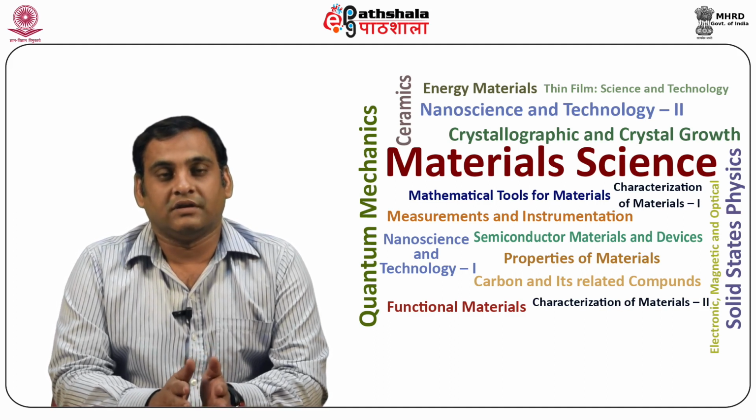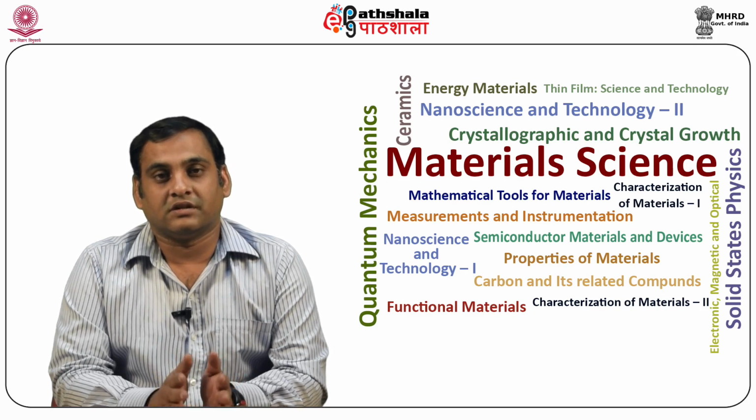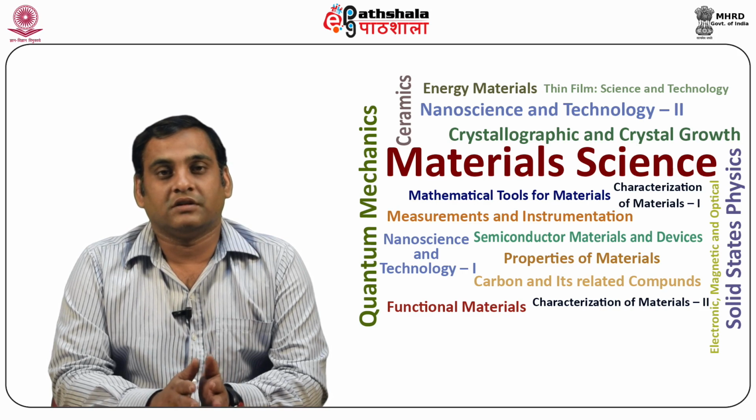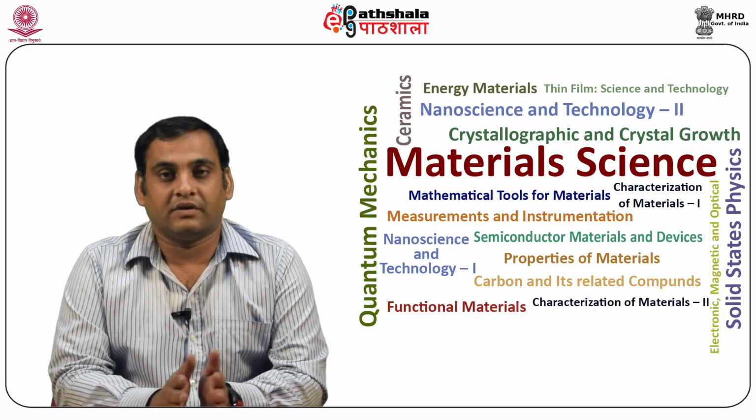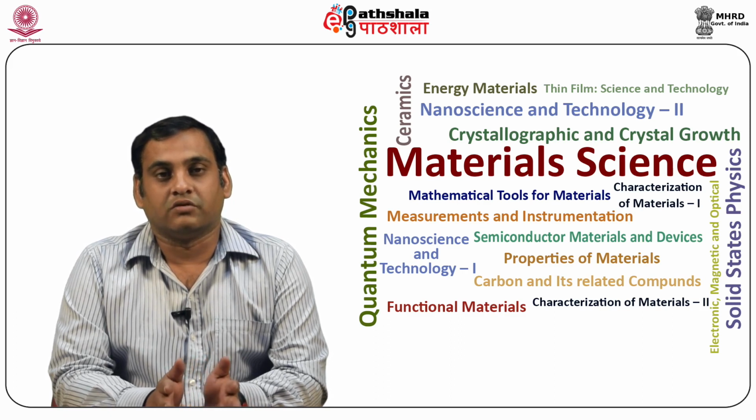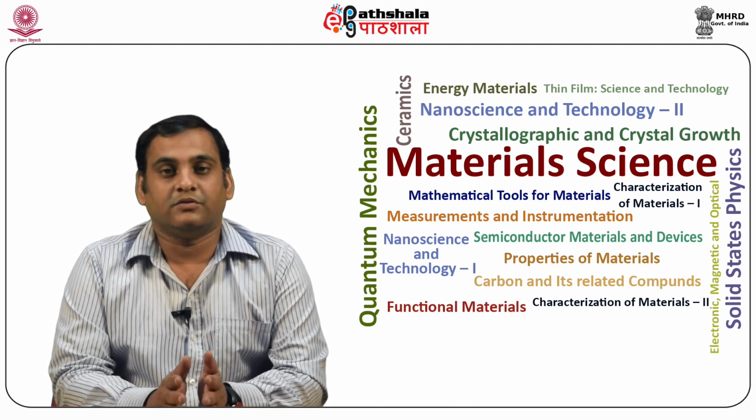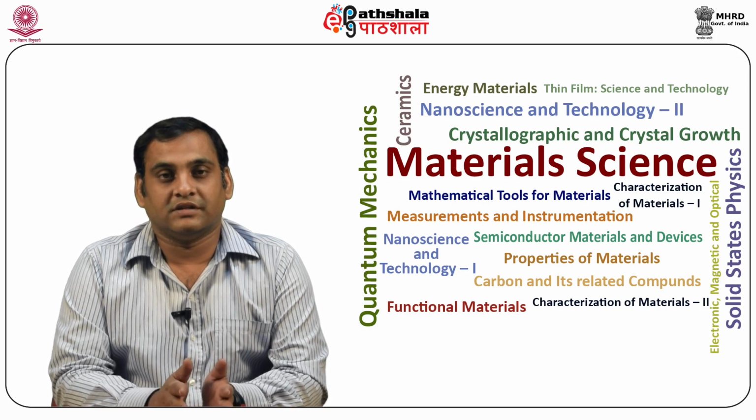Energy associated with a magnetic field. An expression for the energy associated with a static magnetic field may be obtained by considering an inductor L consisting of a current loop which creates a flux phi equal to L times I. By Faraday's law, epsilon is equal to minus d phi by dt, where epsilon is the electromotive force, or EMF, developed in a circuit and phi is the flux threading it. So, the power needed to maintain a current I in the inductor is epsilon times I, equal to L I dI by dt. Integrating from 0 to I gives an expression for the energy associated with the inductor: epsilon is equal to half L I squared, which is equal to half phi times I.